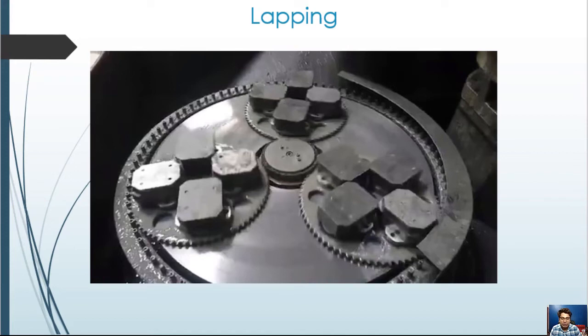The ultra precision machining method of lapping is followed, according to the desired surface quality, by the polishing process. In polishing, the components are pre-lapped in order to achieve high material removal while maintaining a good surface quality and dimension and form tolerance. Polishing is then performed in order to create the highest surface quality, including a mirror finish surface. Lap surfaces exhibit almost exclusively undirected processing traces, a semi-gloss appearance, and when under strain are distinguished by little wear.